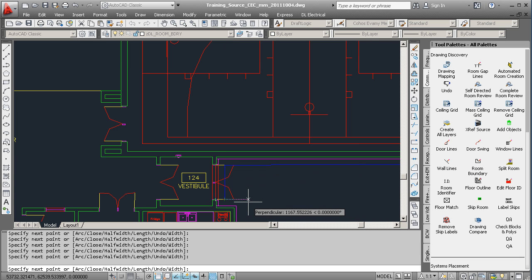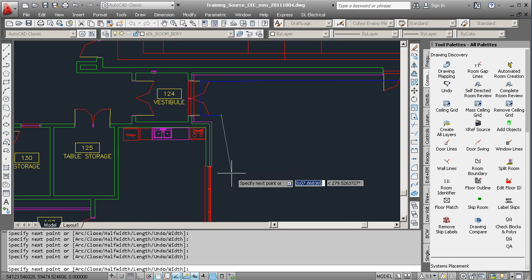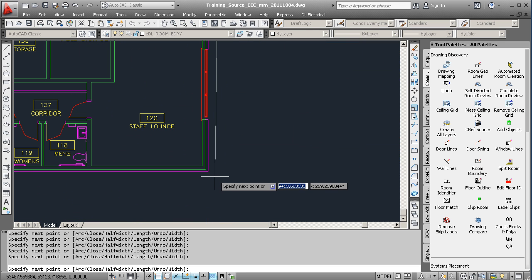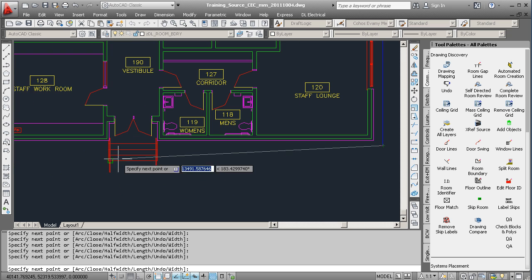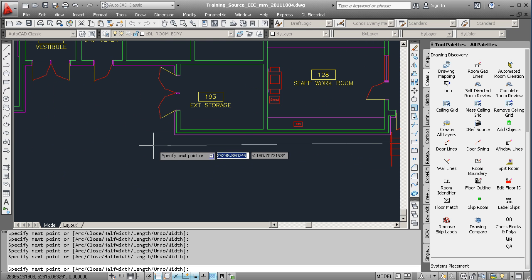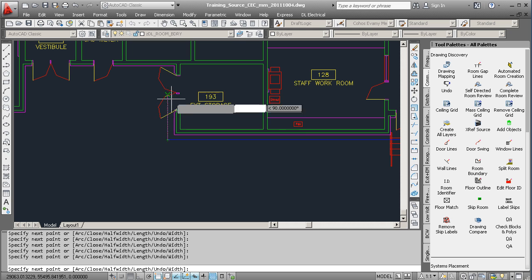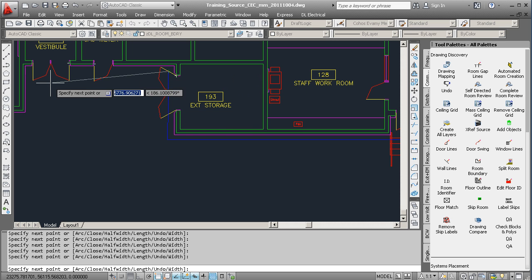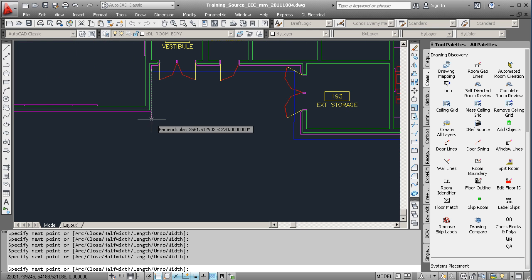So I'm just going around approximately the exterior of the building. If I wanted to have good branch circuit wiring automatically done, I would go a little tighter. I'd go to the actual exterior line, except of course leaving space where desired for those exterior lights and plugs.